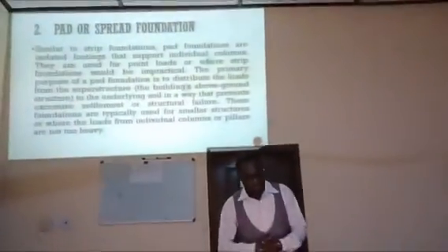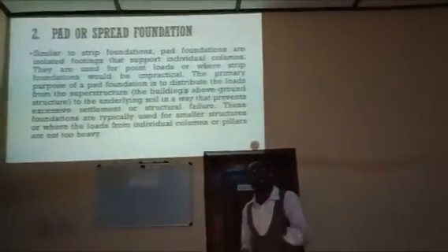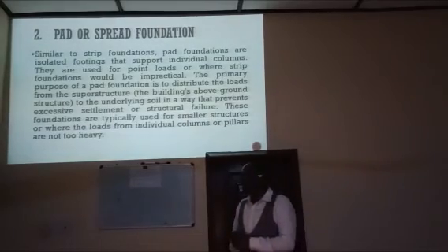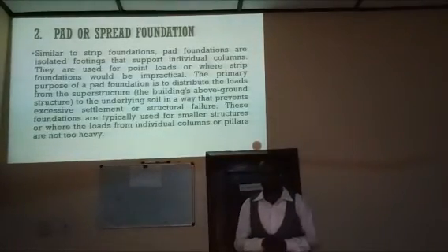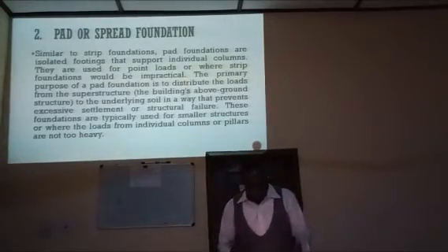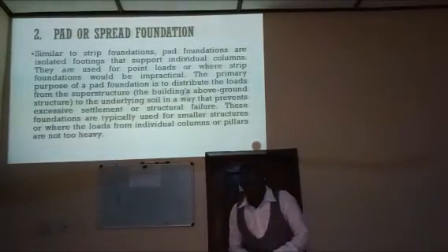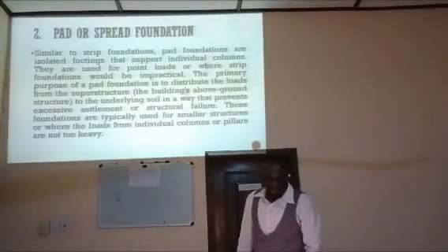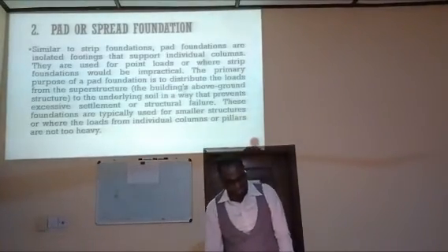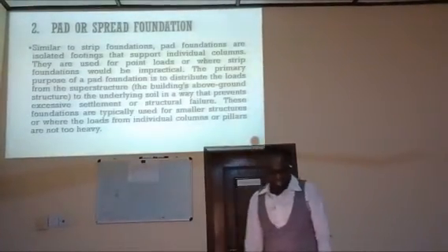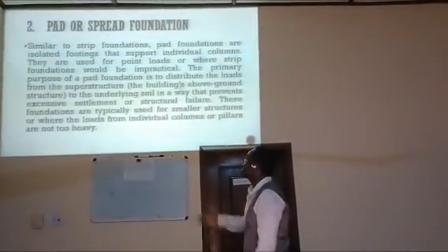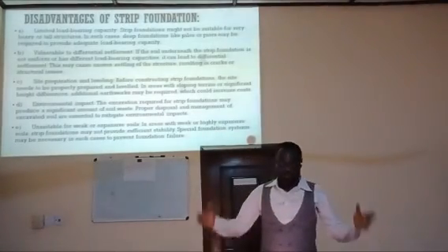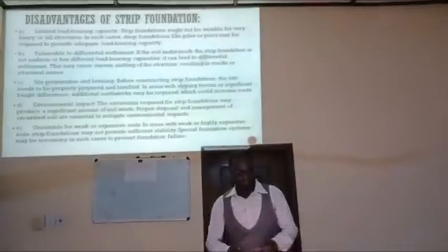Please, next page. There are some features of pad foundation. Number one is the design and construction. Every pad foundation is constructed with reinforced concrete. The size, shape, and depth of the pad depend on the load to be supported. So the bigger the load, the bigger the size of the pad foundation. But before you do a pad foundation, there must also be a soil investigation so that we can determine the properties, the characteristics of the soil, and the bearing capacity.